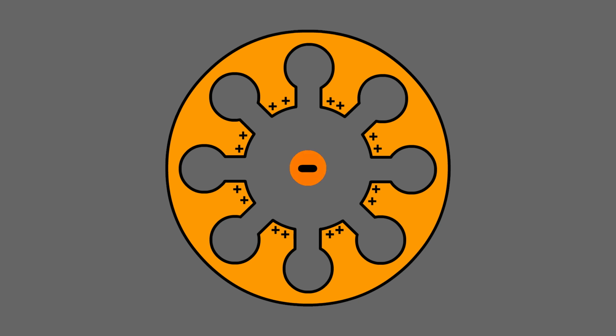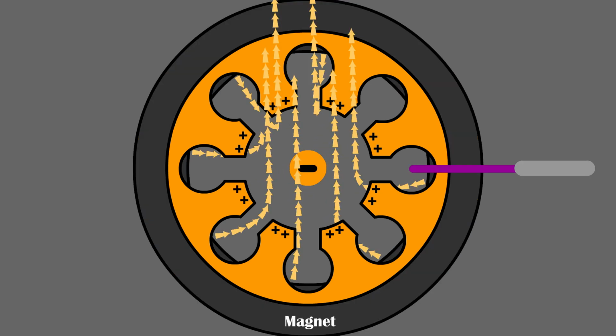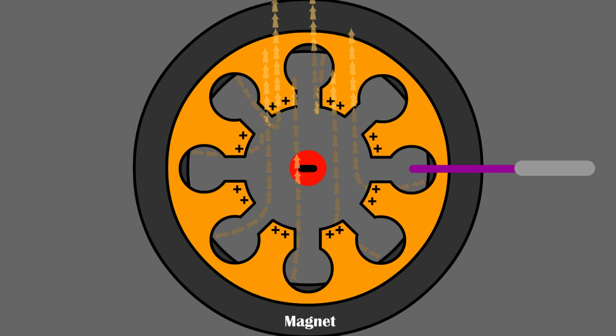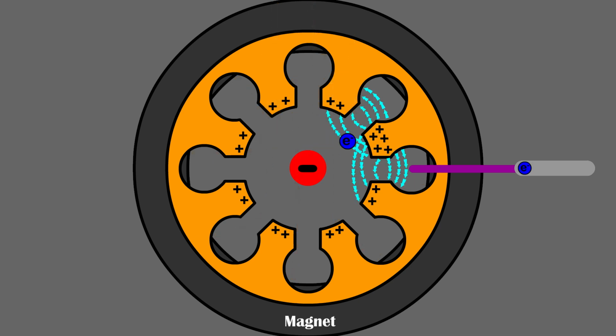If this mechanism were operated without additional intervention, the electrons emitted from the filament would be directly attracted to the positively charged metal, allowing current conversion but preventing microwave generation. If a magnetic field perpendicular to the velocity of the electrons is applied between the filament and the positively charged metal, the electrons will be forced into a spiral motion due to the Lorentz force.